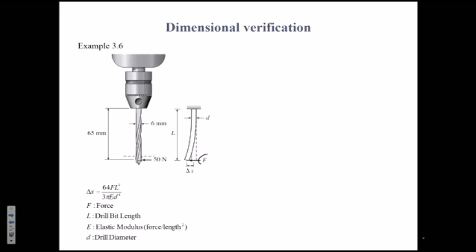So if, let's say, you apply this force F, because the part that you're trying to drill a hole through is moving in a direction perpendicular to the length of the drill, then essentially it deforms the drill bit a little bit, right? If the material it's made of is very soft, then it could deform more. If it's very rigid, thicker, then it's not going to deform. But to some extent, all materials will deform, right? That deformation may be very small, but there is some deformation. So this is known as a cantilever, right? Because it is being held at one point, and you're applying this force. So you'll see this cantilever beam model a lot in your studies, okay?